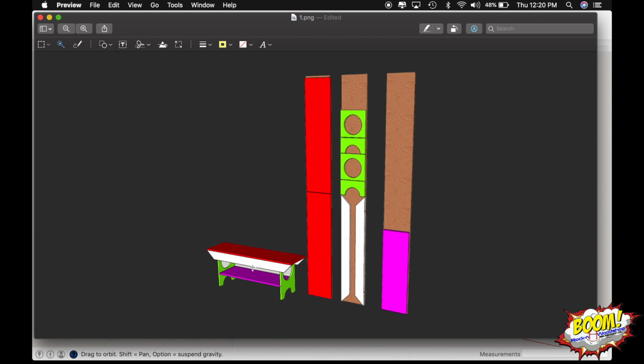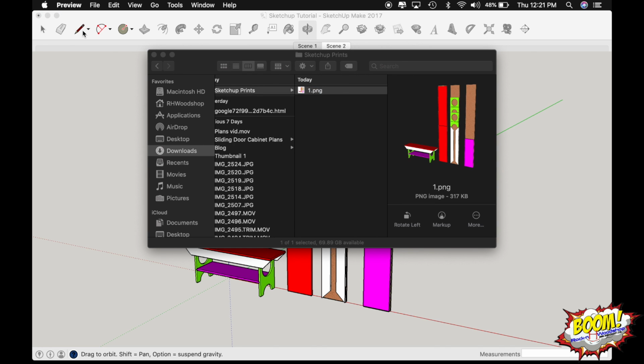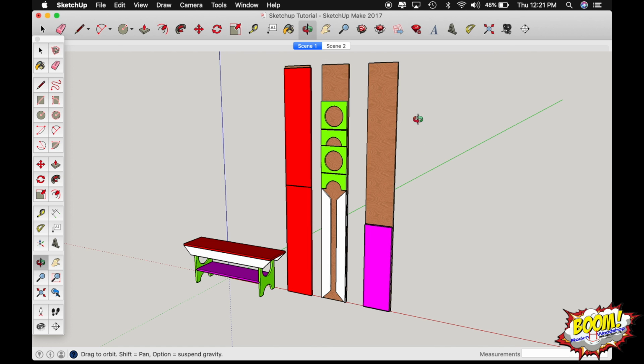You can remove this background that you see back here, back there. It's basically just like the masking area. You're just taking it out of the equation. And then when you're done with that, you just print that on a sheet of paper. Really simple. So you're not actually printing from SketchUp. You're actually saving a PNG exported file, 2D graphic, into a folder, and then you print from there.